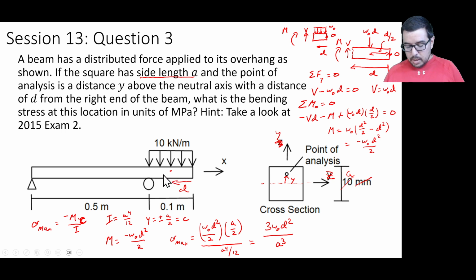And that can be done, but this is an example where, in hindsight, the simpler way to solve this problem is going from the right, where there are no constraints on this free end, and we can, without too much difficulty, figure out how to calculate, like we did over here, just through equilibrium, the internal bending moment and the internal shear force.